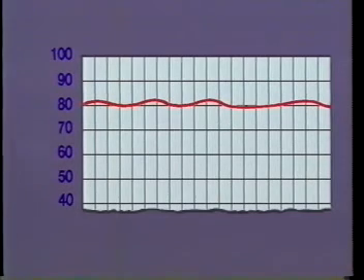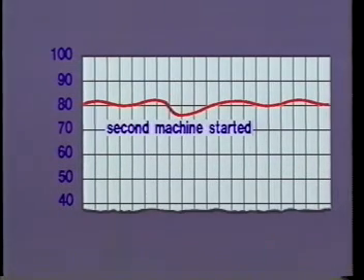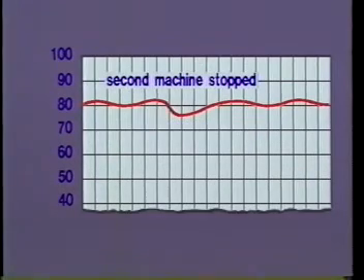With one bottling machine in operation, very satisfactory control was obtained. When the second machine was started, note that some deviation took place. The valve was temporarily opened to allow a large inflow of steam, and the temperature did not drop below the limit for good product. When the second machine was shut down, the reverse action took place. The valve was temporarily closed, and temperature did not exceed the upper limit. The control instrument was therefore in full command of the process. The plant could operate at peak performance day after day with no waste.